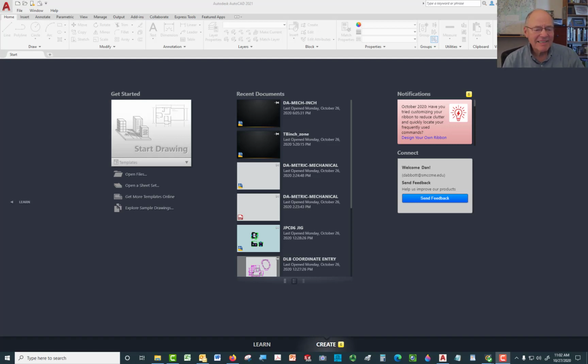It's actually easier than it sounds, because most of the time in a mechanical title block you can make a title block and put it in different size borders for the different sheets. This example is going to be an imperial title block, but you can use it for metric as long as you modify any references to inches by increasing the size of the title block by 25.4.